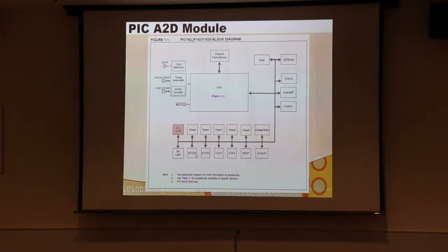But for purposes of PWM, we can use them as single-ended where they behave in the same way. But if you want to use a full bridge or a half bridge, you can use 1 or 2. And then we have these master synchronous serial ports, which is the SPI and the I2C. We have 2 of those. And we have the UART.